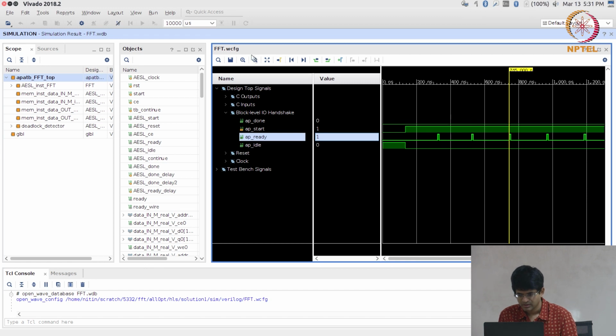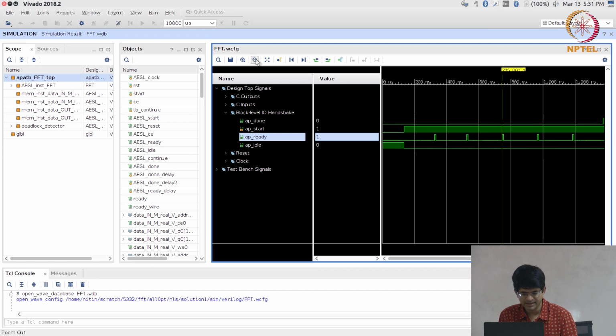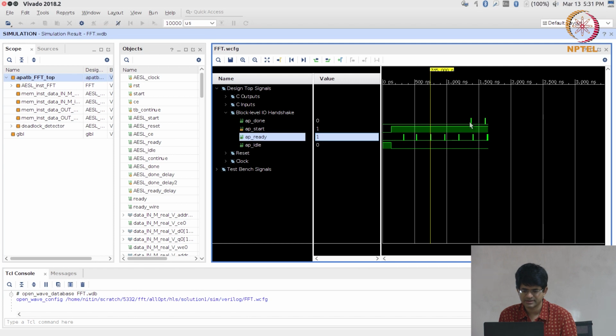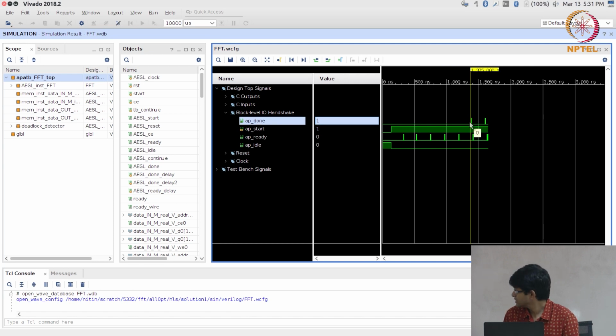Okay. Where is our done signal? Here it is. Okay. So, the difference between the done signal and the start signal corresponds to 124 clock cycles. That is where it got the measured latency from. Okay. And you can see that 20 plus 25 times over here plus something else, this is around 124 clock cycles.